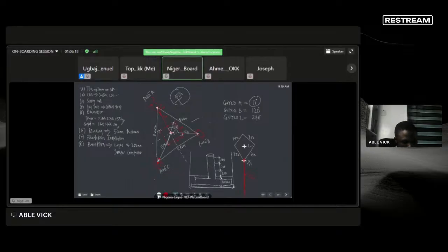For each layer you backfill, you need to compact. For the next layer, you compact with your jumper compactor. Fill it with water. Backfill the next layer, you compact, fill it, and keep on like that until you get your layers.